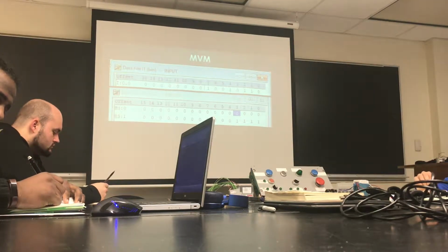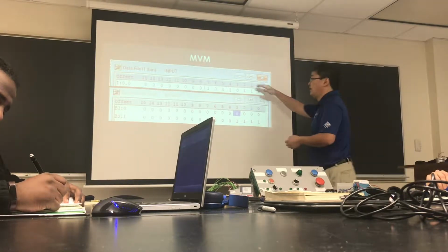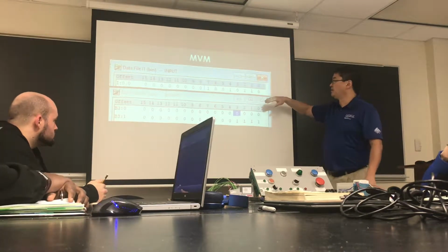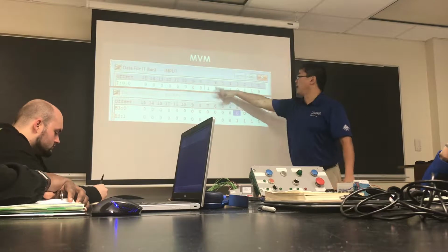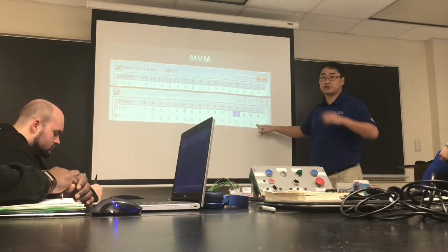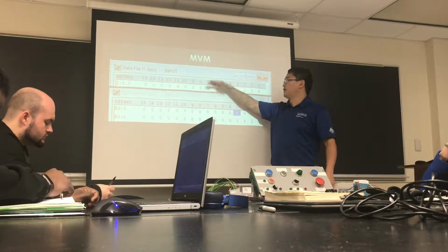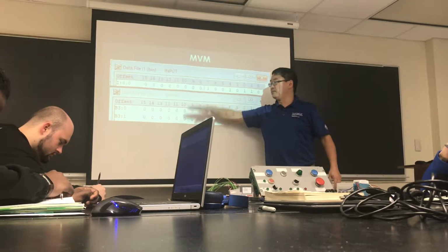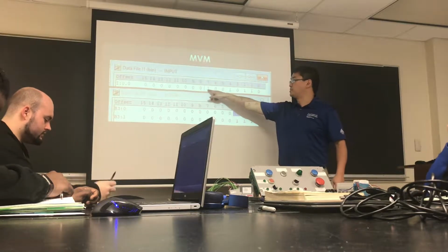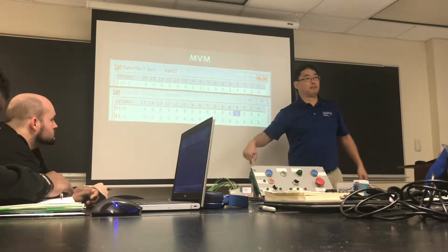So if I have my input, and where I'm headed with this is the whole BCD, binary coded decimal thing. So if these are my inputs, and I've got something on here and something on here and whatever, but I only want to copy the first 4 bits and ignore everything else, if I do a straight move, it's going to take all 16 and move it down to my destination. And so whatever this binary decimal BCD value of this is, would get put in my number.